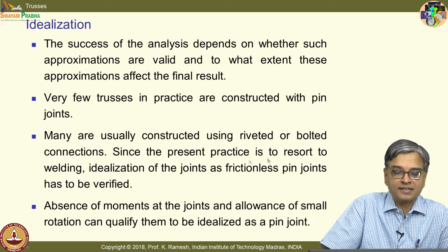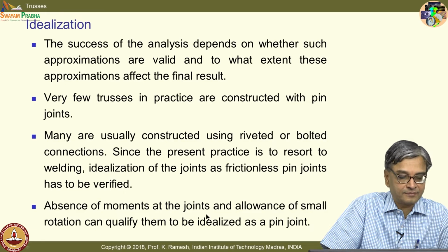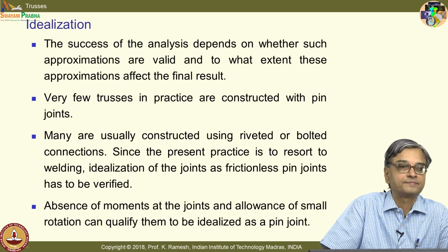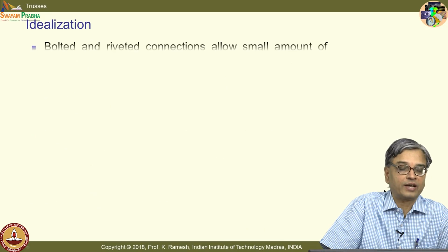Since the present practice is to resort to welding, idealization of the joints as frictionless pin joints has to be verified. Absence of moments at the joints and allowance of small rotation can qualify them to be idealized as a pin joint. So, that is what we are going to look at.